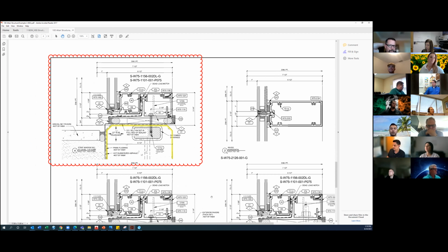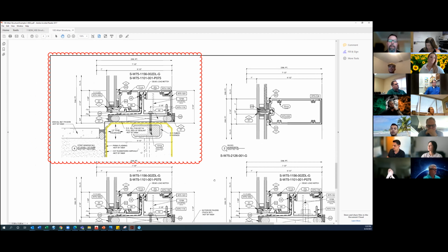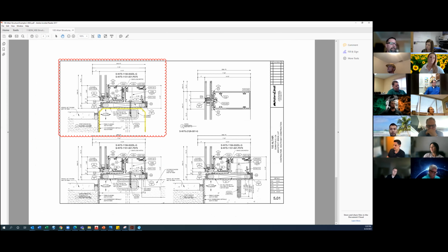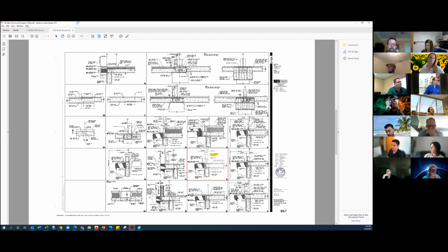You have to remember that people don't build off of our drawings, they build off of the contract documents. Had we thought that this was a flat curb or went further back, our system or layout could have been wrong, and our drawings could have been wrong. So I think it's an instance where we really focus on the architectural drawings and what they show, and then the steel guys focus on the structural drawings and don't necessarily look too much at the architecturals. If we don't cross-check, then we end up building something that doesn't match or doesn't necessarily align.